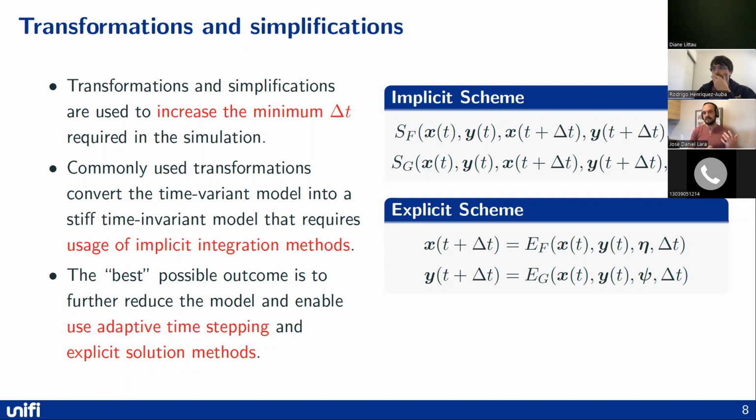So if we think of a system, for example, a single line with 9 states at a discretization of 1e-9, if we wanted to go to that level of detail, just the data of that one line will produce about 30 gigabytes worth of outputs if we were to do a full waveform at that level of discretization, right? Which makes it clearly unmanageable even with current computational capabilities.